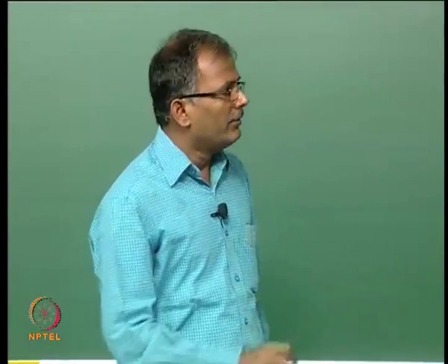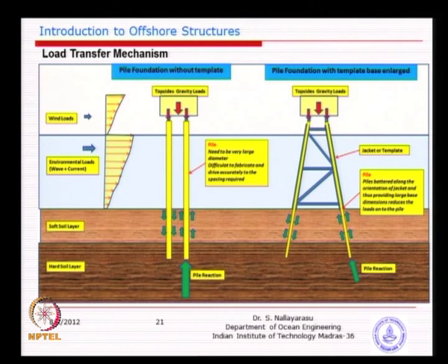So, if you see in this picture, the spacing of these supports has to be pre-arranged. Now, installation of these piles at pre-destined distances between each of them has to be very accurate. If you install by half a meter incorrectly, because this is already fabricated, isn't it, when you bring it and install on top, the support points may not match. So, what will need to be done? You either need to change the location of the pile, which proves to be very difficult, number 1, or you have to change the superstructure.